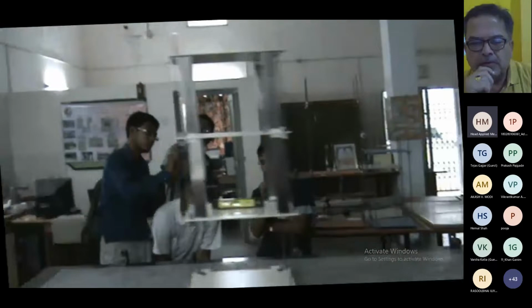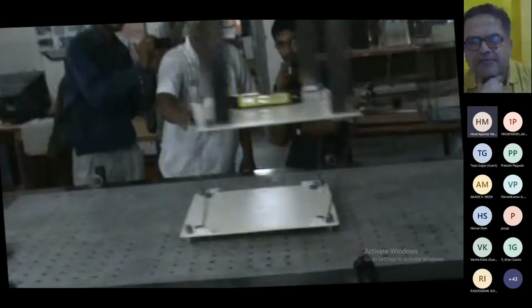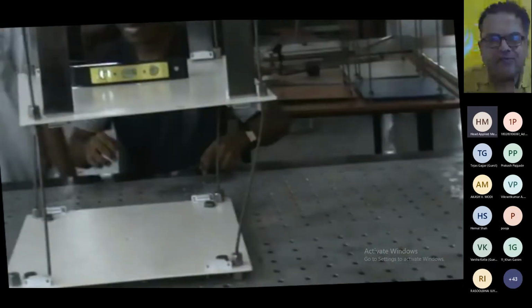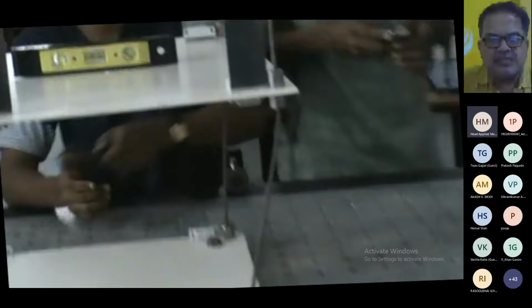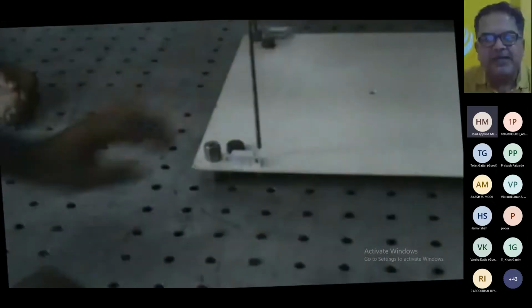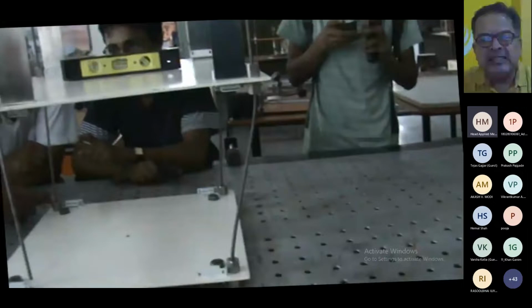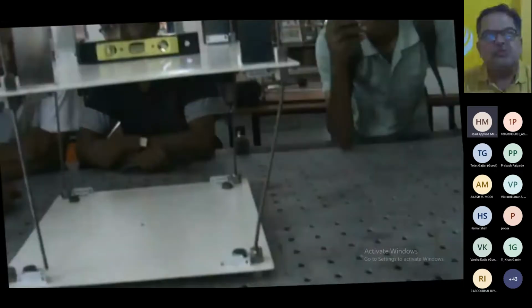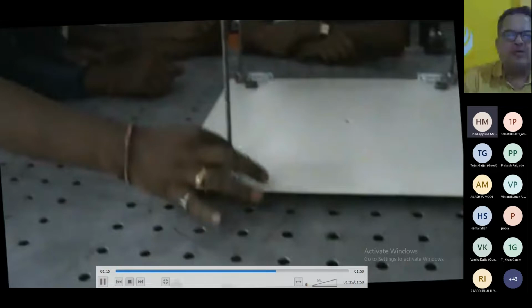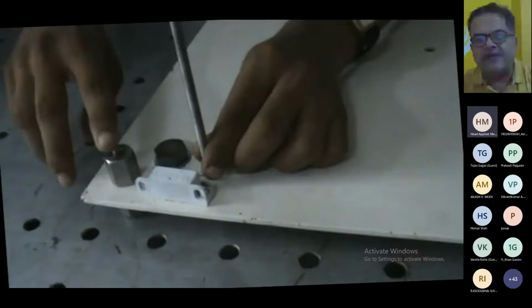Now vibration continues, and what happened? Deformation. After so many cycles, because of the reversal of the stresses, it fails, right? And a lot of energy is released. So you can feel heat there. This structure is not able to absorb the energy supplied to it, right? So this is known as a soft story failure, or open ground story failure.